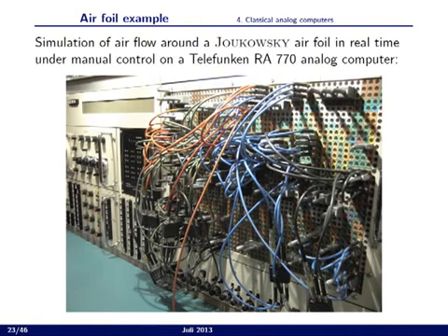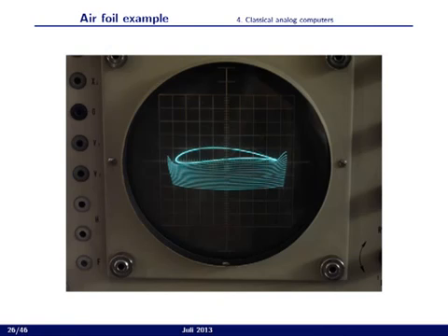The result looks like this. This is the completed program, and a simulation run looks like this. I can compute 16 air particles in different positions below or above the airfoil in real time. And not only in real time, I can compute it faster than real time by pressing a simple switch, like 10 times faster, which does nothing else than speed up every integrator by a factor of 10 by exchanging its integration capacitor. It's just brilliant.